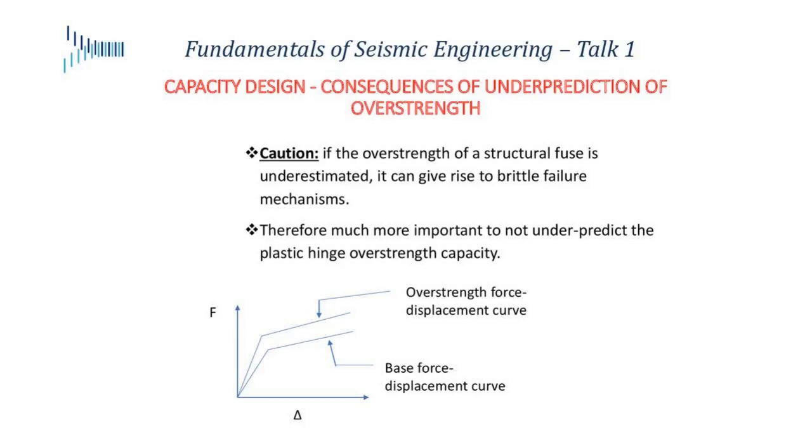If you take a concrete sample and crush it, and let's say its strength was supposed to be 35 MPa or 4 ksi, if you give it 56 days or 2 years, in all probability it will be 25-30% stronger. If you take a piece of reinforcement, which is 400 MPa or 60 ksi, and do a tension test on it, you'll find that it will be 10, 15, 20% stronger than what you designed it for.